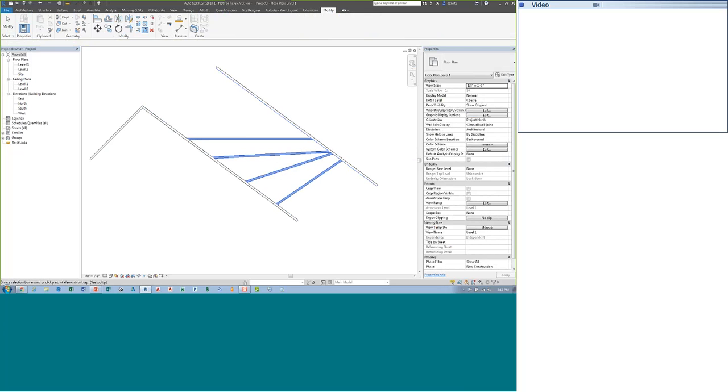Now, when you're picking, you can do individual picking like that, or, I'm undoing, you can do the trim extend and do a window crossing like this, and the trim extends all of them. Okay.